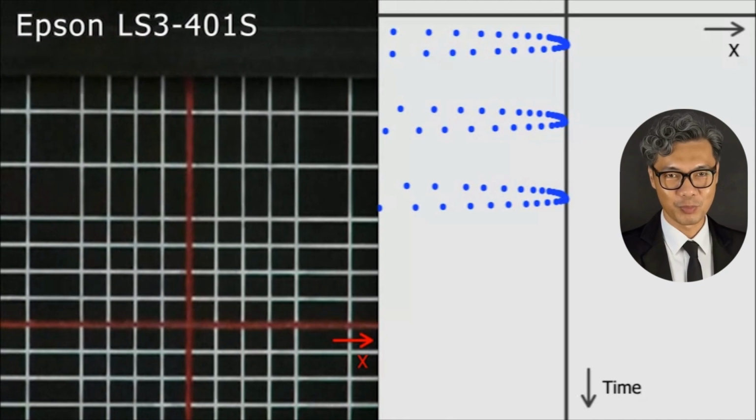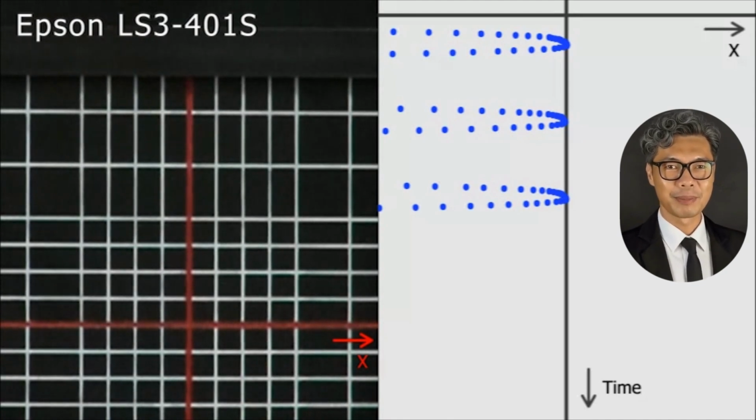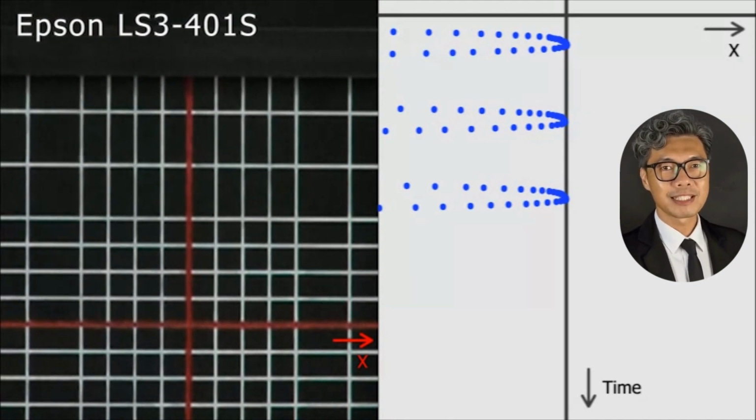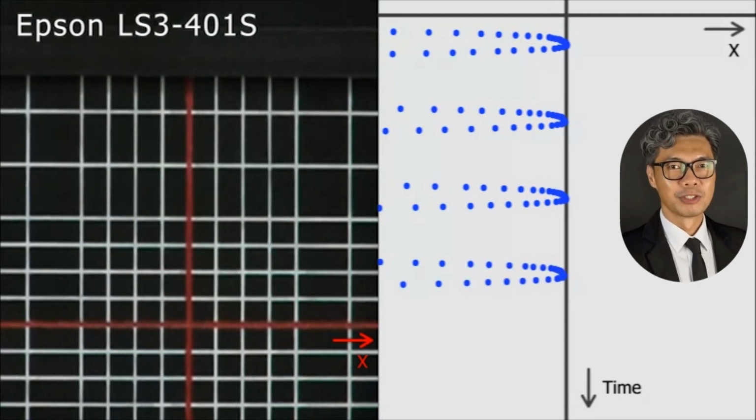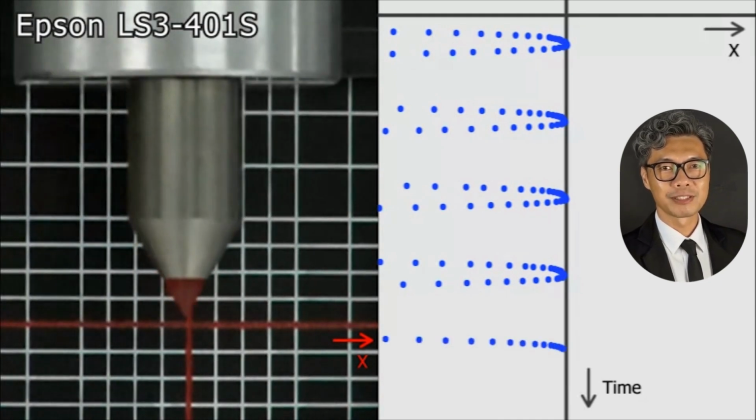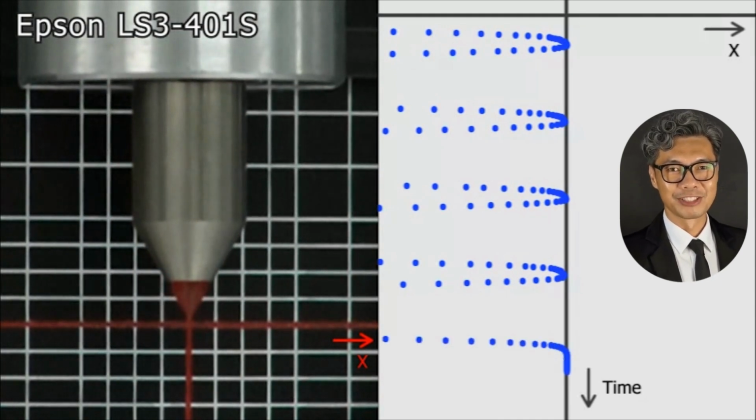These are applications where a Delta robot's speed advantage means nothing if the placement is not exact. SCARA robots also handle vertical insertion well, which makes them suitable for any process that requires pressing, inserting, or seating a component precisely into a socket or housing.